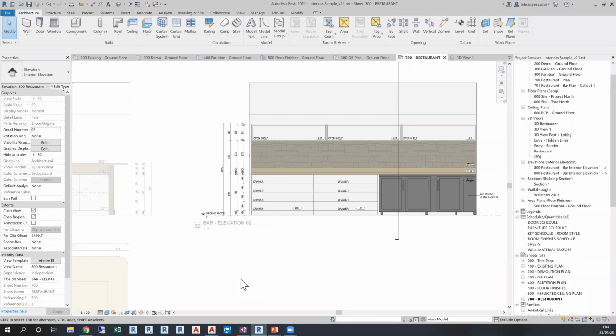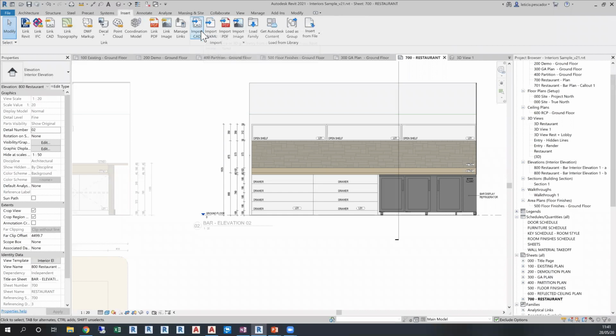When you're doing CAD drawings in Revit, there are workflows to follow best practices to avoid issues, but those issues are usually related to users importing CAD drawings instead of linking, and also when people start exploding CAD drawings. And there are workflows that can address that. Usually we can fix it, so we can remove those drawings, or we can try troubleshooting, but it varies drastically from file to file.